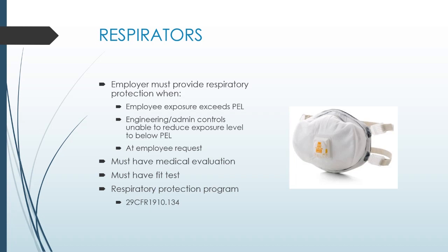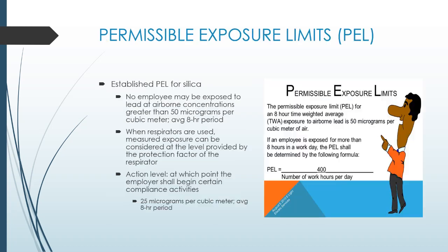We use the N100 particulate respirators by 3M. They protect against silica dust. I see on job sites a lot of guys using those N95s, and they don't protect against that. Not only that, you have to be fit tested for them, and I don't think a lot of people are. If the wrong person were to come and you're wearing an N95 respirator because you think it's a dust mask, and they ask, hey, are you fit tested for that? And you say no, that's a $4,500 fine per person if it's our first offense. So we don't want that, obviously.